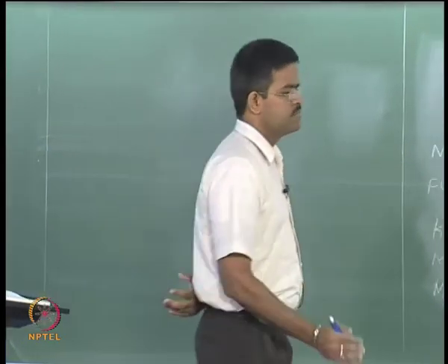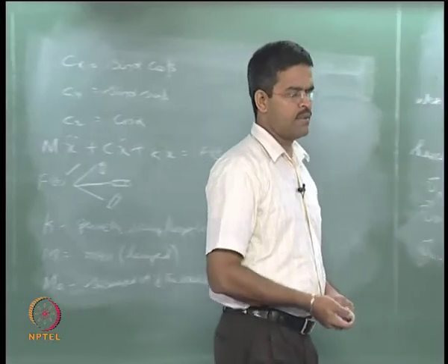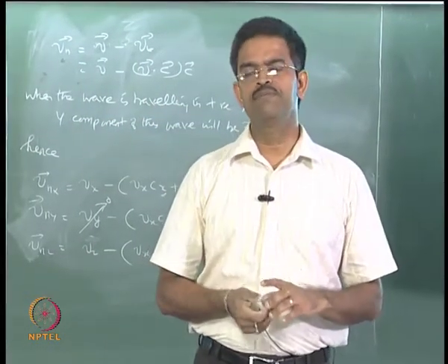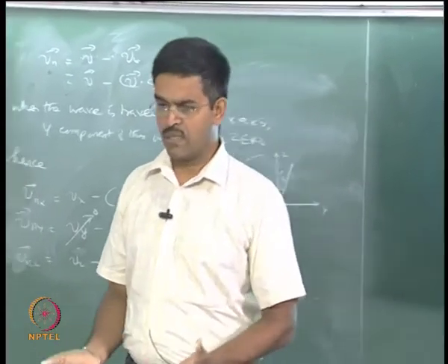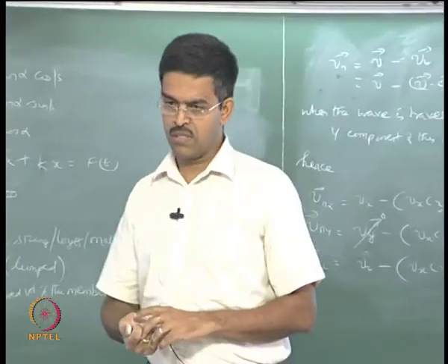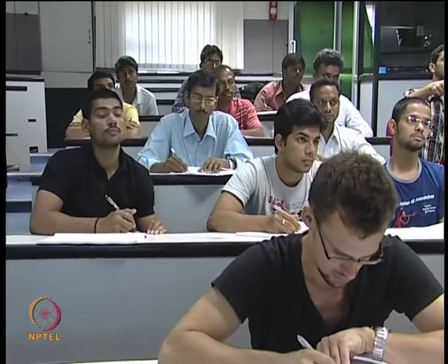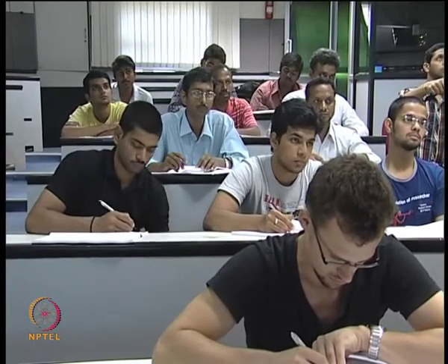Any questions here? So, I can handle vertical members, horizontal members, inclined members. I can also linearize the drag term, which is one of the nonlinearities present in the system because of the multiplication of the velocity vector component with the force in Morison equation.